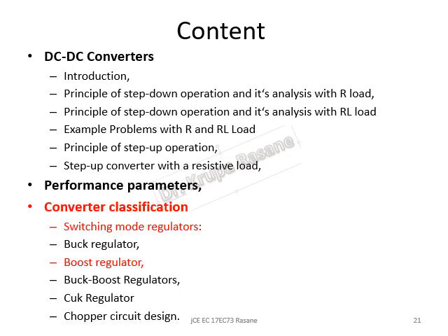So we have been looking in this particular video into the switching mode regulator with respect to the boost regulator. We have seen the circuit diagram, we have seen the modes of operation, we have done the derivation for the output voltage, the ripple current, the ripple voltage, and also we have evaluated the critical value of the inductor as well as the critical value of the capacitor to get the continuous load current.